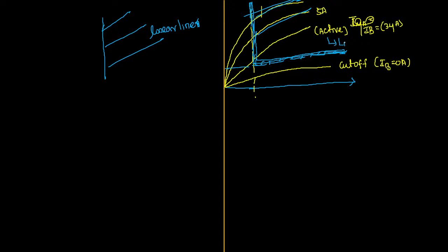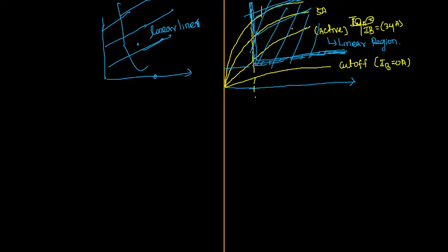That's why this region is also called a linear region, because in the active region your transistor characteristics will be linear. Linear means what? With respect to x-axis, if there is any change in x-axis, immediately in y-axis also the change will be reflected and it will be linearly increasing like this. So I can call this entire zone linear or active region, just to remember it. Now, one more zone is there, the cutoff region. Already I kept that, so let us enter into that point.